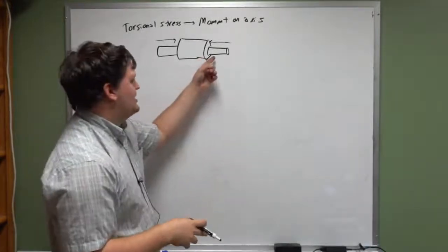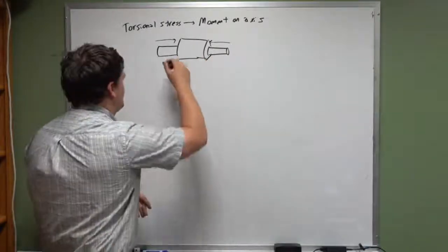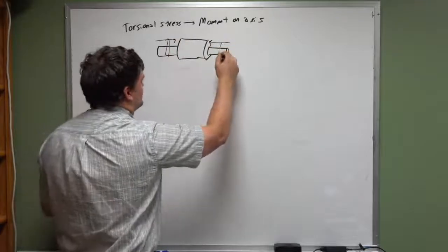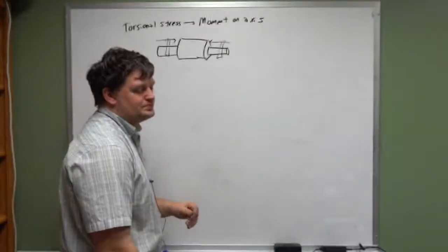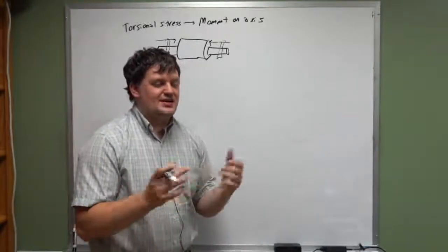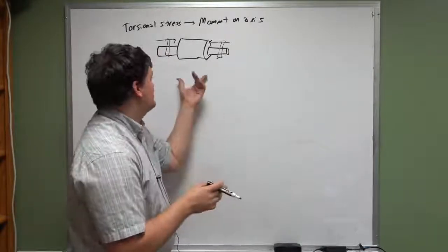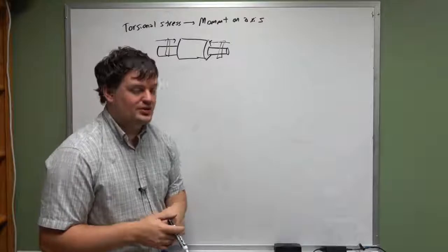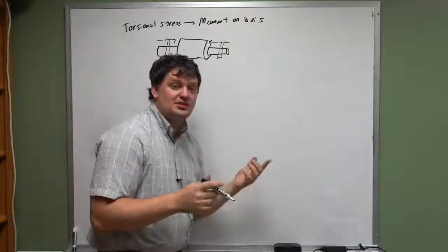You basically only have to pin one end of it and have a gear or something on both sides if you need to. It just makes the entire mechanism work nicer when you have that step in the middle. But it does make the math a little different.